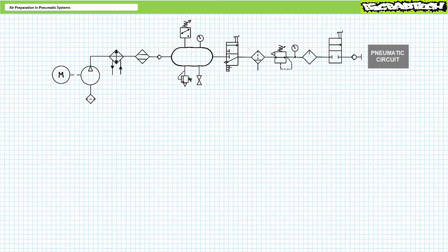Luckily, we have a safety pressure relief valve. Experiencing pressure above and beyond the set value of the pressure switch and approaching design limits of the receiver, the safety pressure relief valve vents to atmosphere, often with a startling burst of noise.